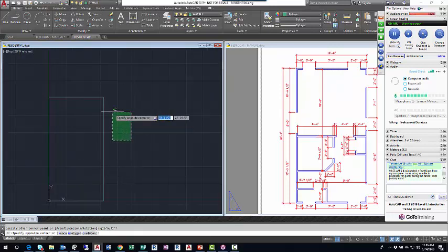Once you have it drawn, it's a good idea to double check the dimensions. And I'm going to do that by selecting the rectangle and hovering over one of the corner points. It can't be one of the edge grips. The edge grips will give you a different menu and no measurement. The corners will give you the XY in this case. I'll hit escape to deselect that.